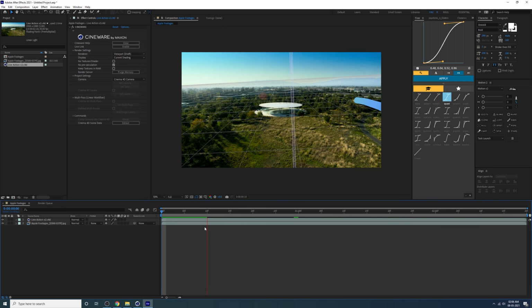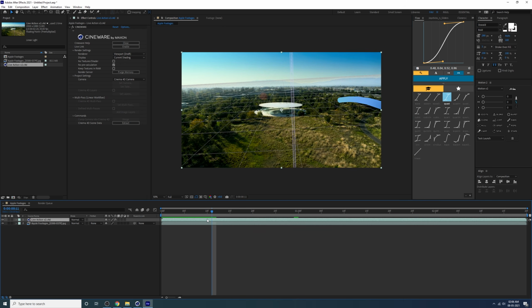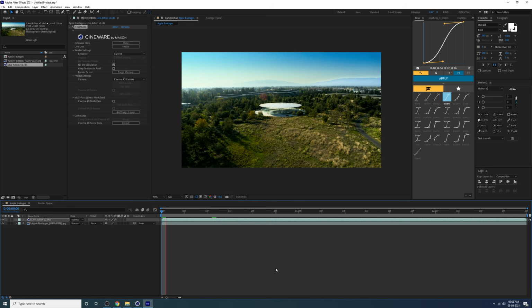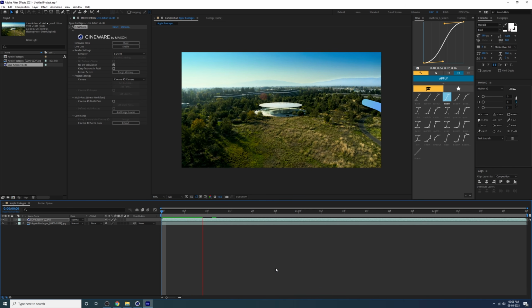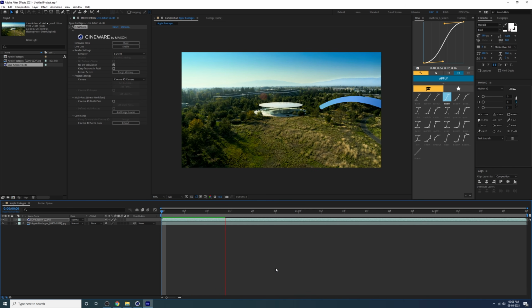Yes. Now to render in proper ways, select the Cinema 4D, and in FX controls you can access the Cineware properties. Change the render type into current, so they'll remove all this grid and everything, the final output. Now just press the space bar. You can preview the video.